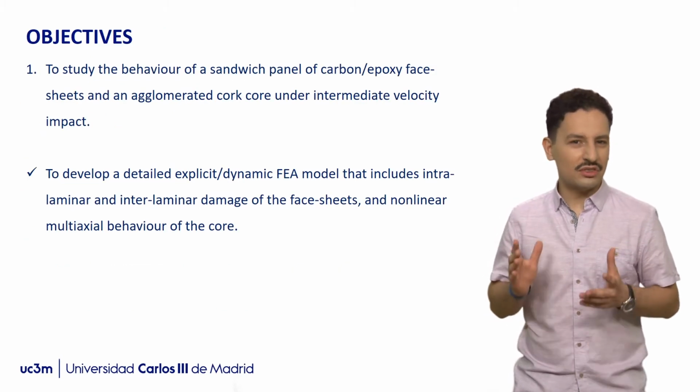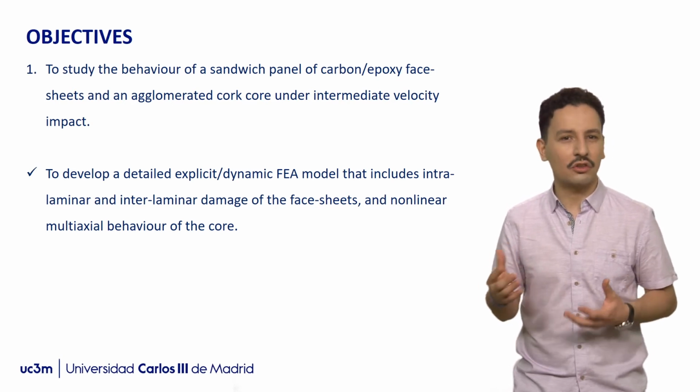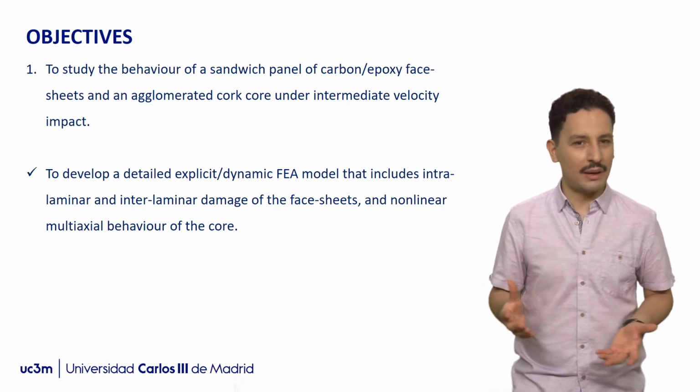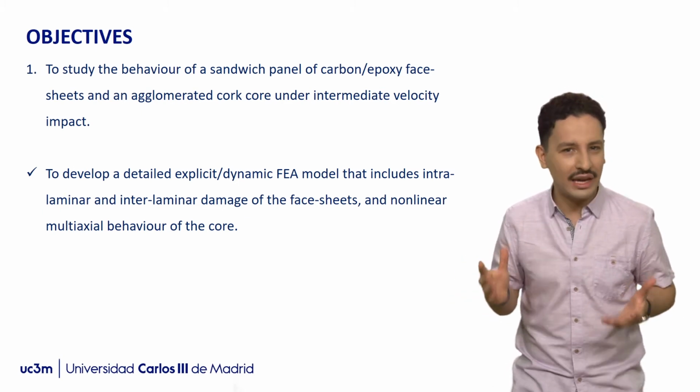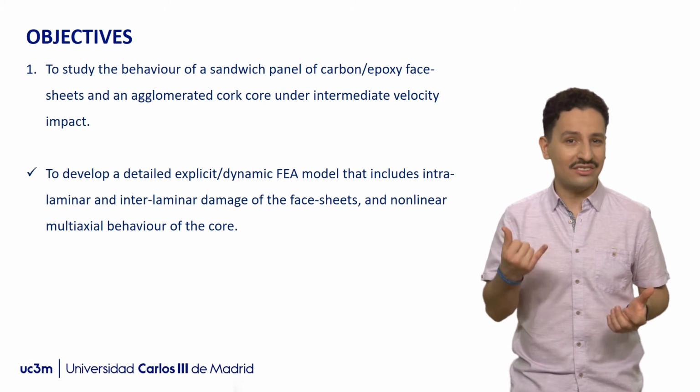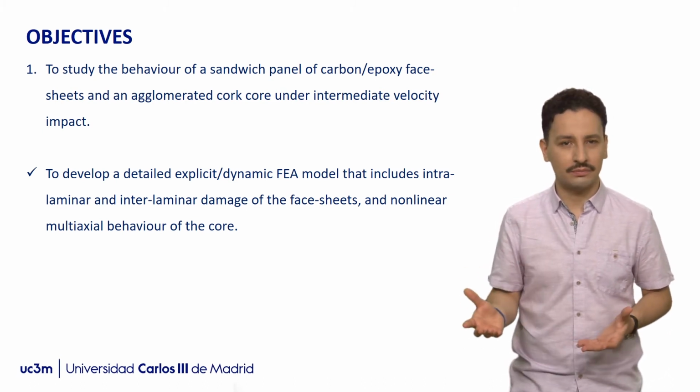Our objective is to study the behavior of sandwich panels of carbon epoxy face sheets and agglomerated cork under intermediate velocity impacts. We did that by developing an explicit dynamic finite element analysis model that included intralaminar and interlaminar damage, as well as the core's nonlinear behavior.